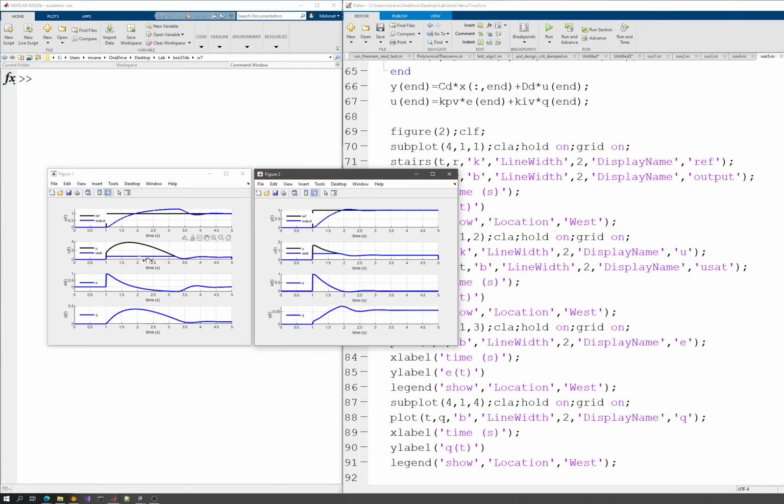And if, for example, your controller is not able to enter the linear region back from the saturation, or if it's not able to escape the saturation, then your system will become unstable. And this anti-windup structure is needed in that case, because the system has limitations, which is most of the time the case in real-world applications, and your controller is not aware of this restriction, and your implementation or design method does not involve saturation.